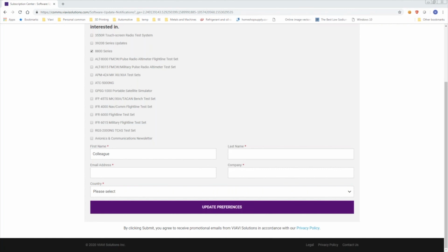Mike, you mentioned the frequency response of your cables, and what you're seeing there is pretty typical. Yes, as you go up in frequency, your loss is going to increase in that cable. So in your case, you talk about VHF being about 0.1 dB, 800 meg being about 0.2. I would say that's pretty typical. And again, that's going to vary depending on how long the cable is. It's going to vary depending on the type of cable you're using. But the general trend would be the higher in frequency you go, the more the cable loss is going to affect your measurements.